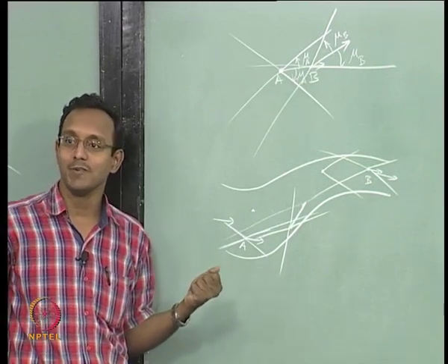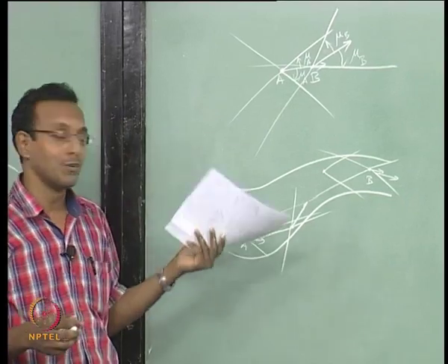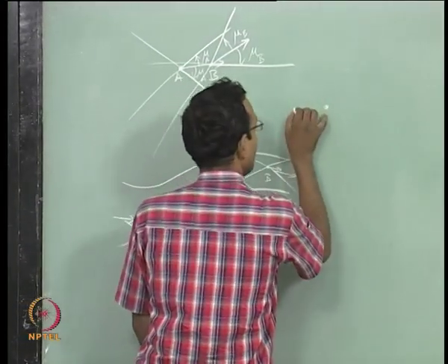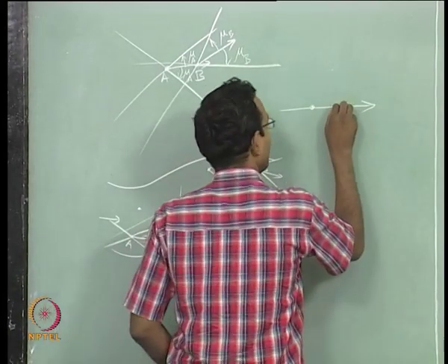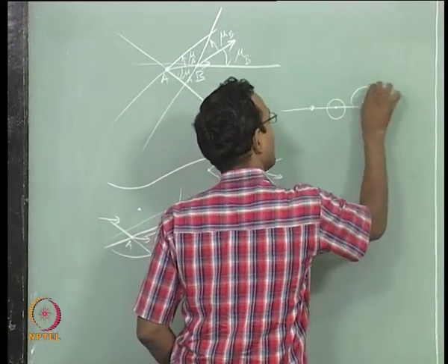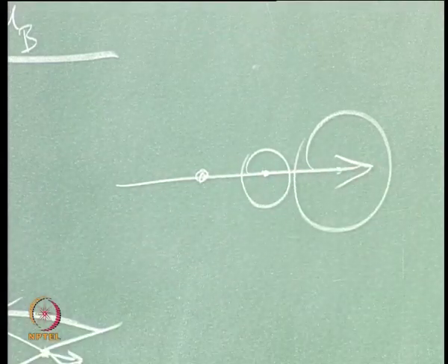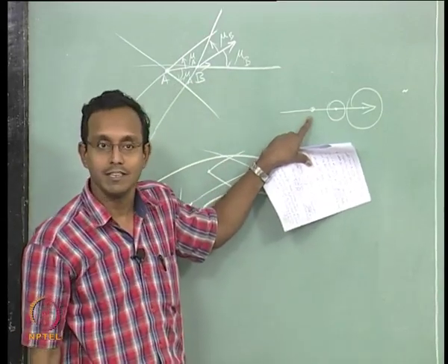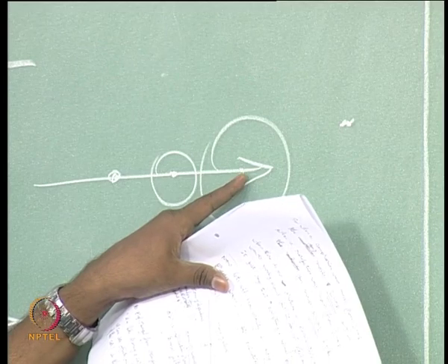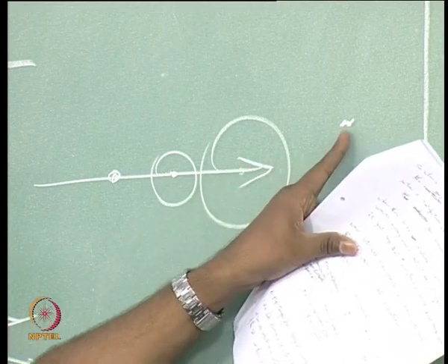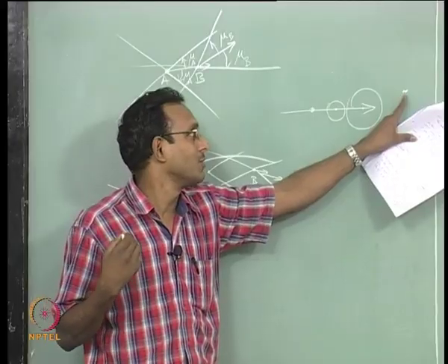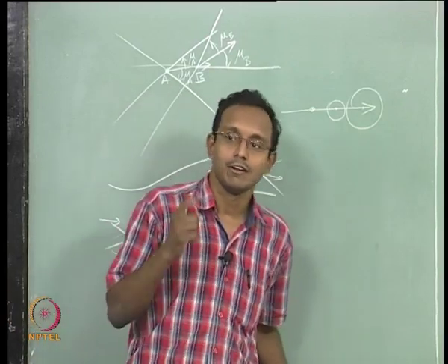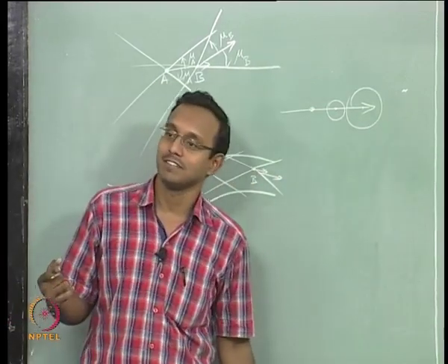Okay. If it is unsteady, what happens? If it is unsteady, I am going to think about that animation we had yesterday, where I just now created a disturbance and the fluid element is carrying it. At this point it is going to be this big, at this point it is going to be this big, the disturbance is just now growing. So, even this point is currently not influenced by this change at this instant when the fluid element is here. When this goes some more distance only, it will be getting affected. The picture we have drawn about zone of silence and zone of influence are all for steady state conditions. Remember that when we go to unsteady, things may not be exactly the same, it will keep changing.